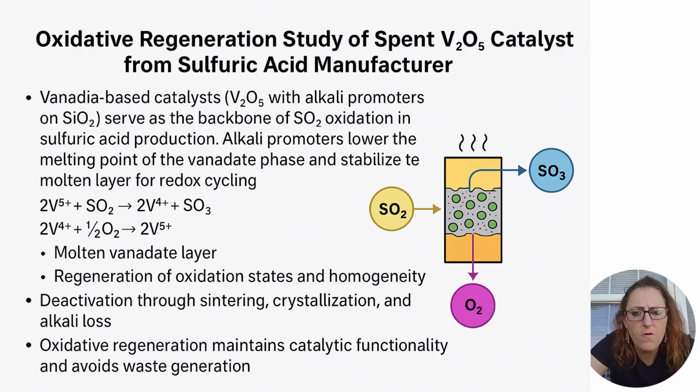The work focuses on evaluating regeneration efficiency under controlled oxidative environments, specifically 5% oxygen-nitrogen versus air. Using a well-designed fixed-bed quartz reactor system, these findings contribute to both industrial process improvement and reaction engineering design principles for catalyst performance and sustainability.